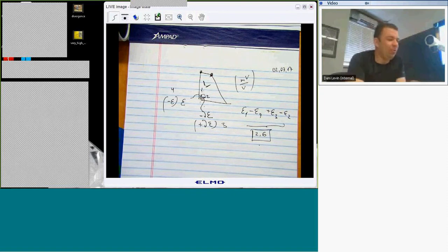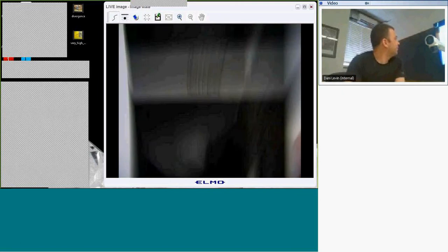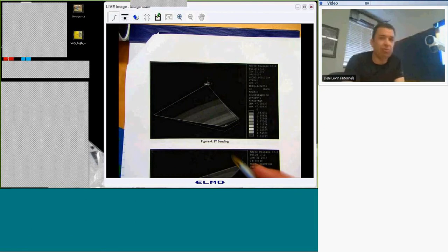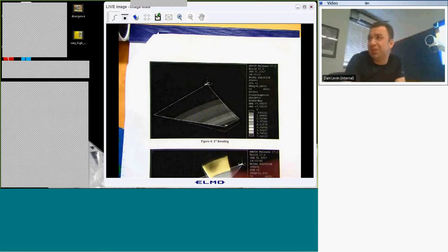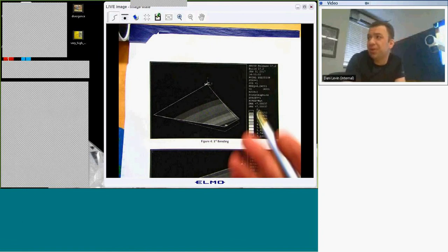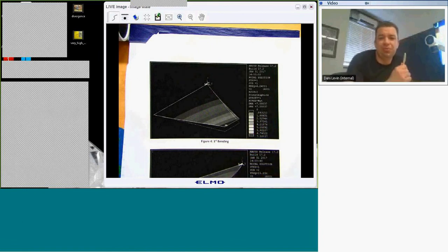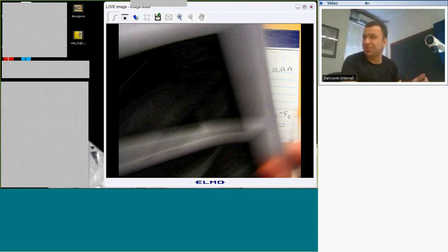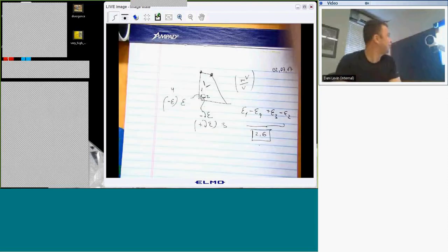One other thing about the modes is the way that we name them. So let's say we are talking about not a simple plate, but an aircraft. In aircraft, you also have the first bending mode. But the thing that you need to remember always is that in first bending mode, wing bending mode, all of the aircraft responds. It's mostly bending mode, but all of the aircraft is in motion. This is very important for when you do your test and some manager comes and asks for it. So it's a very good answer.